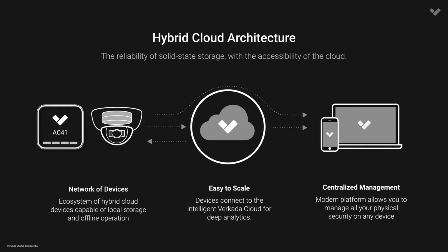Each camera connects directly to our servers over PoE, Power over Ethernet, but thanks to that local storage, we're not constantly streaming footage, which in the past can strangle bandwidth. We upload just thumbnails and metadata in our steady state, giving us a normal usage of only 20 to 50 kilobits per second on the network.